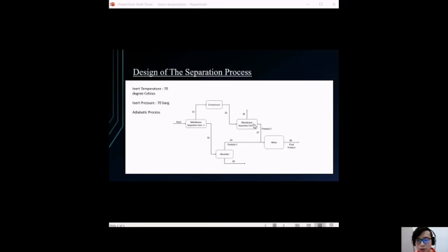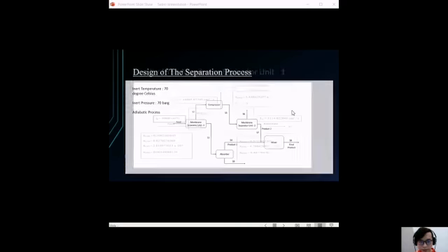After the second membrane separation, most of the carbon dioxide and hydrogen sulfide will be removed from stream 6, and we will get the second product at stream 7. Lastly, the mixer is used to combine the first product and the second product. The final product is formed, which is in stream 8. The final product is the required purified natural gas, and it should achieve the required specification. The whole process is assumed to be an adiabatic process.